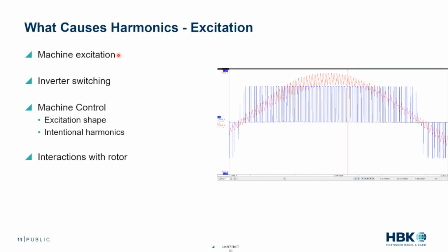And inverters, if we remember back to that square wave we showed, that's an infinite series of sine waves. We have a lot of square waves here. We're injecting a lot of square waves into that current, into that voltage. So the inverter switching absolutely can cause harmonics. Those are going to be higher order at the switching frequency. I'm not going to talk about that a ton, but it's there.